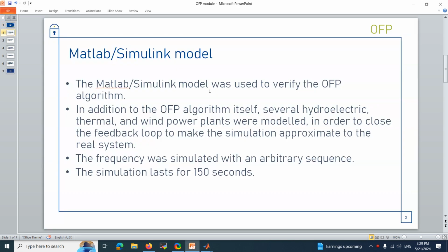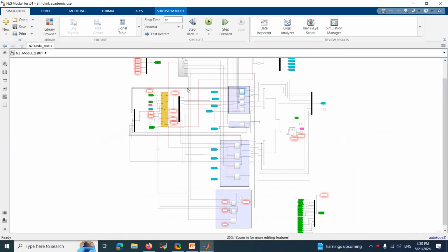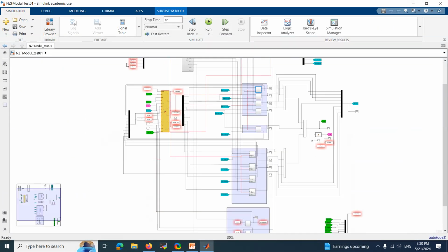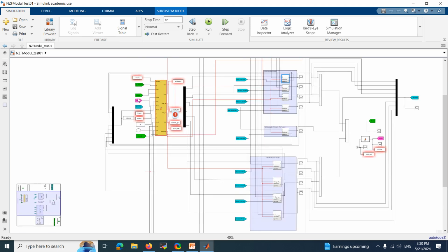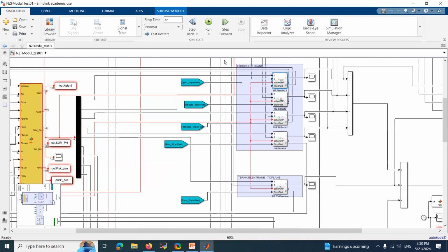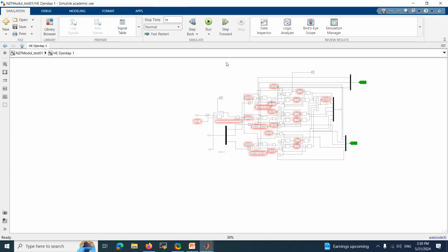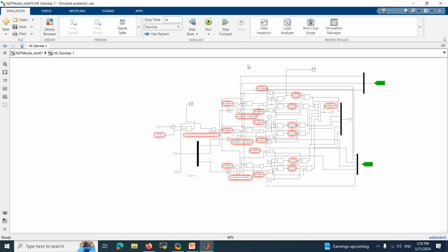Now we will open our Simulink model. On the left side of the diagram is shown a MATLAB function block which contains the implemented frequency protection algorithm. On the other side are models of each type of power plant that you can find in the energy mix of Serbia. Inside every model, for example, hydropower plant J1, parameters of the transfer function are chosen in a way to give real-time dynamics as close as possible, within the limitations and obstacles of a simplified model.